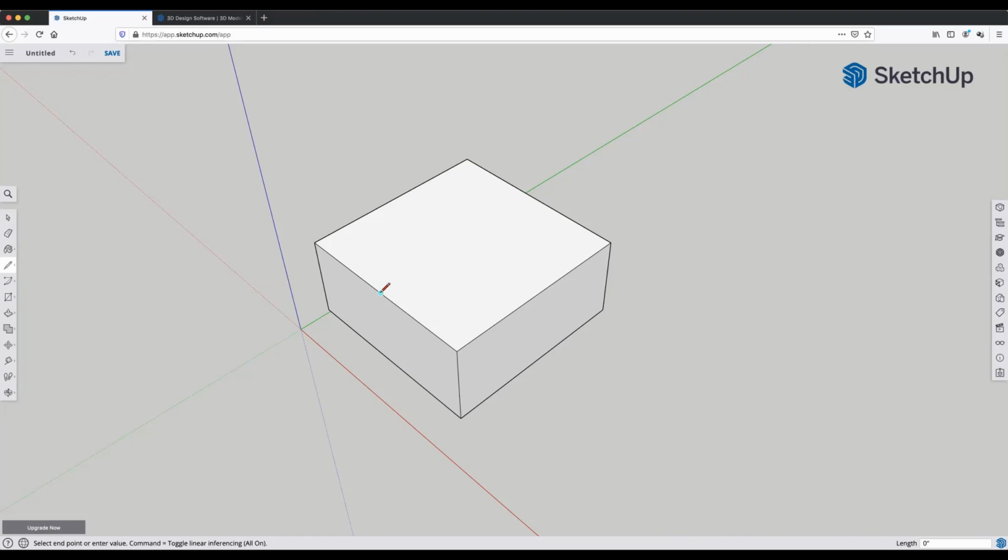So we're going to click right here. So left click once and just move our mouse to the back. Make sure it stays perpendicular with that green. So if we go off kilter, it's going to give us a crooked line. So just go straight to the back and select midpoint, or click on midpoint.